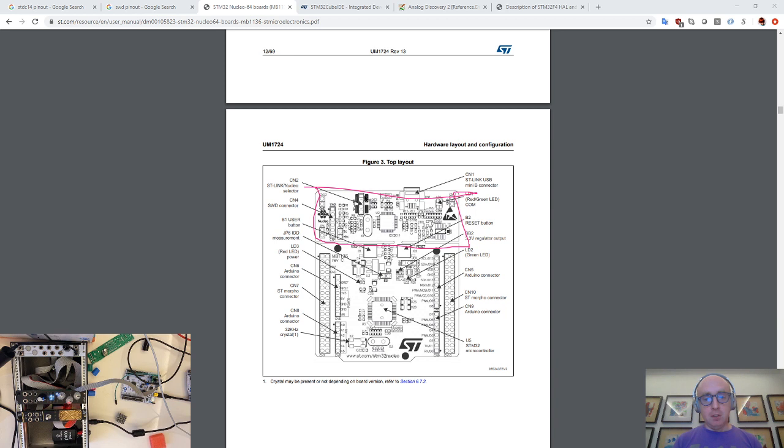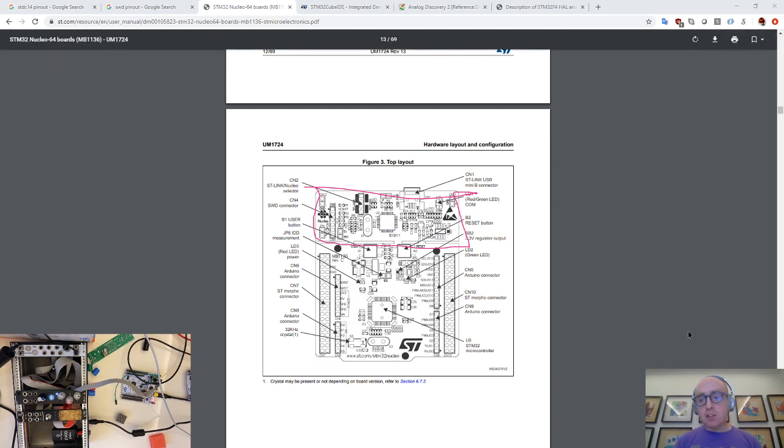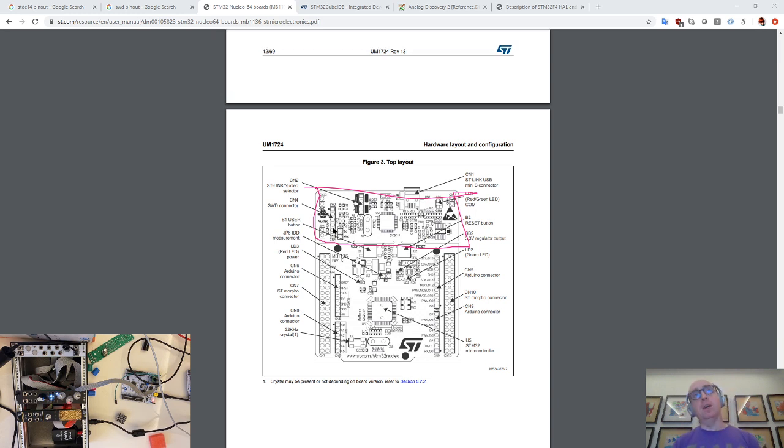So I've got the module in my Pico case. I've got the programming cable going to the Nucleo, and I've got power. So you've got this standalone ST-Link programmer, and it has these stupid 6 pins, which is 3.3 volts going from your design to it, ground, SWO, which you don't need, and then data and clock, basically.